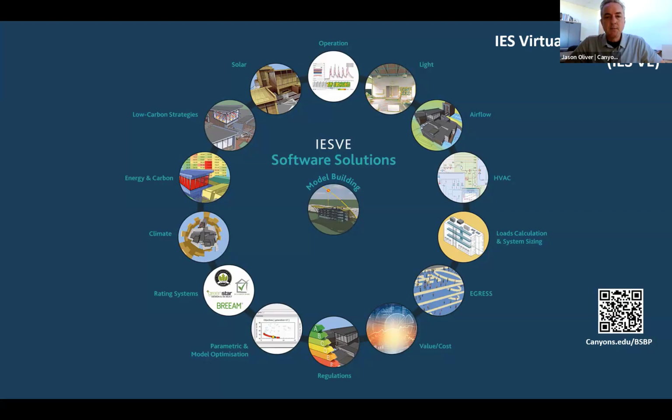of a project that we need for, obviously, creating the spaces and making sure we can accommodate the various programmatic functions for a client, solving the sort of puzzle of space planning for a building. But even in those early stages now, we can start to do things like solar studies and even airflow studies. If we have an idea that we might have natural ventilation for a project, we can start to put in some very simple windows and kind of see how air would flow through a space, through that sort of dynamic modeling.